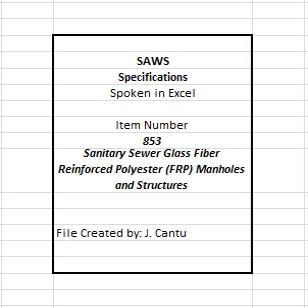and observed. 3. Any measurable loss within a 30-minute period shall be considered an unsuccessful test and thus require the contractor to assess the needed repairs, perform such repairs, subject to the approval of the engineer, and notify the inspector when the retest will be performed. 4. All effort, materials, or other costs shall be solely at the contractor's expense. Vacuum testing. Manhole shall be tested after construction/installation and backfilling with all connections, existing and/or proposed, in place. 1. Drop connections and gas sealing connections shall be installed prior to testing.